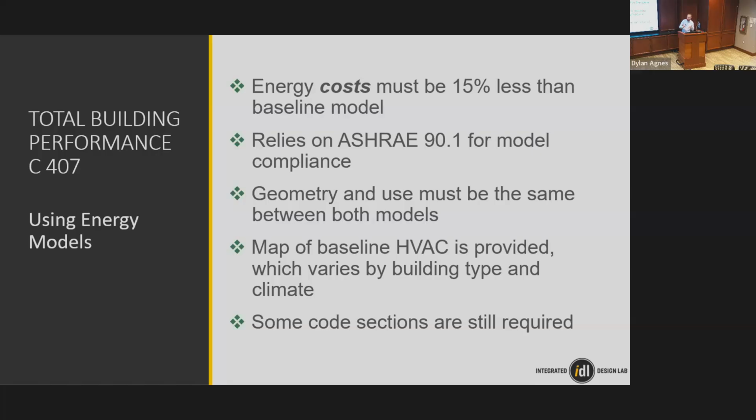So it actually launches you from the IECC code over to the ASHRAE code. It says, look here for how to do a proper energy model. There's a couple pages in the IECC that walk you through the basics. Essentially, you are running an hour-by-hour simulation over a typical year in your climate, using local rates. And you have to make sure that the geometry of both the baseline and your proposed building are the same.